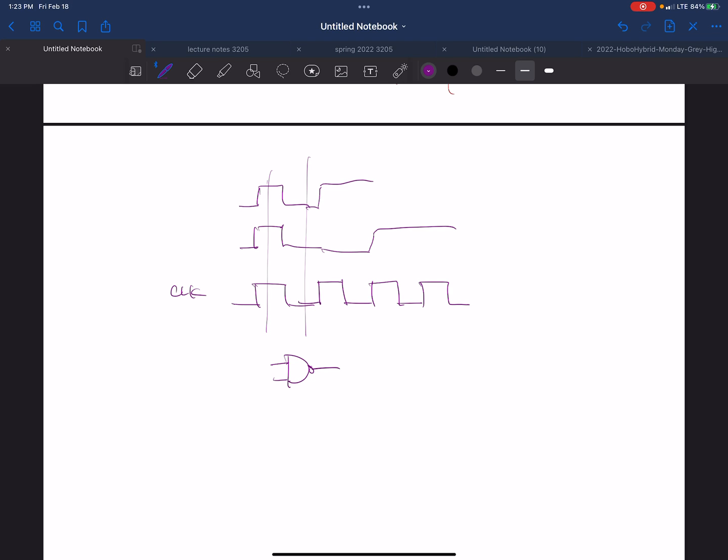We'll talk about this a little bit later, but I like to use the vending machine as an example. If the vending machine was only made of combinational circuits, when you fed it your money, let's say you were using coins, and went to select your drink, it wouldn't realize that there was a time before where money was fed in. Does that make sense? Whereas a sequential circuit realizes, oh, there's a sequence of events here. Money gets fed in.